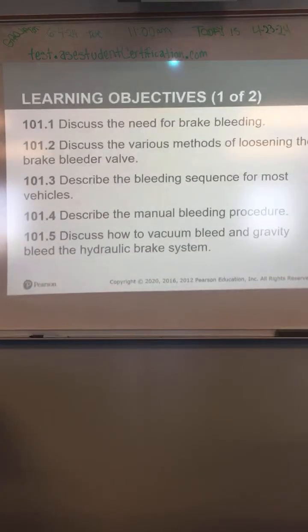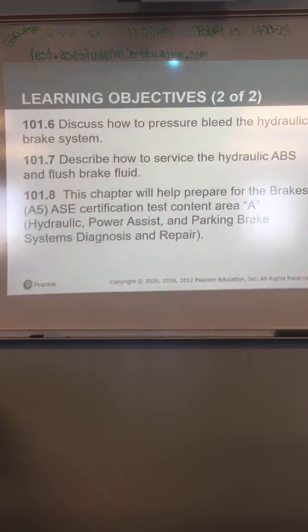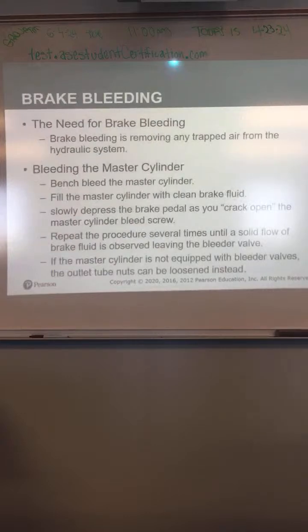We talked about various methods. Sometimes there is a sequence, where they want you to start with the one farthest away from the master cylinder and work your way to the closest one. Manual bleeding procedure, vacuum bleed, gravity bleed, pressure bleed, which we talked about. How to service the hydraulic ABS and flush brake fluid. Brake bleeding removes any trapped air from the hydraulic system.